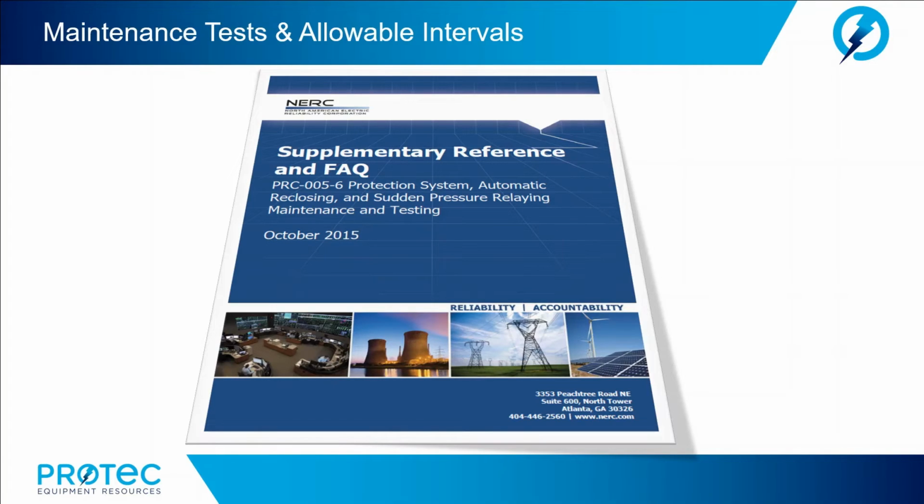Now, IEEE standards 450, 1188, and 1106 for vented lead acid, valve-regulated lead acid, and nickel-cadmium batteries, respectively, which are the most used station batteries on the NERC bulk electrical system, have been developed as an important reference source of maintenance recommendations.